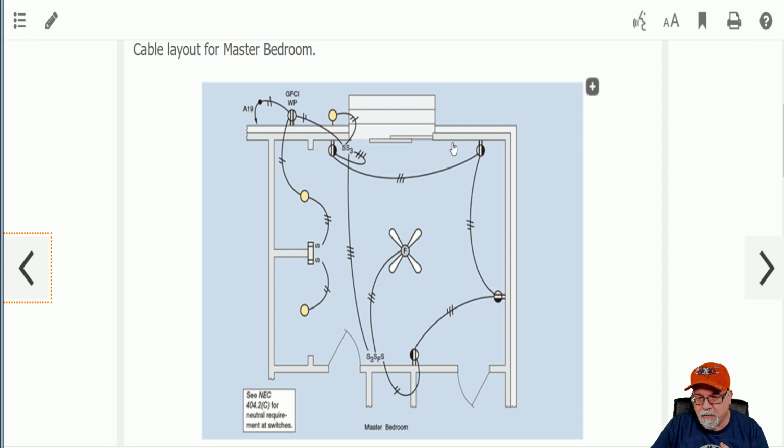Maybe I put it back here, but then I go 12 feet and it's right here. Well, here I've got to have a receptacle within 6 feet of this break in the wall line. So if this receptacle was still back here, then I would not have a receptacle here. I've got to add another one. So that would result in having 3 receptacles on this segment between this opening and this opening right here. That's okay. That would be code compliant, but it's all about the spacing.